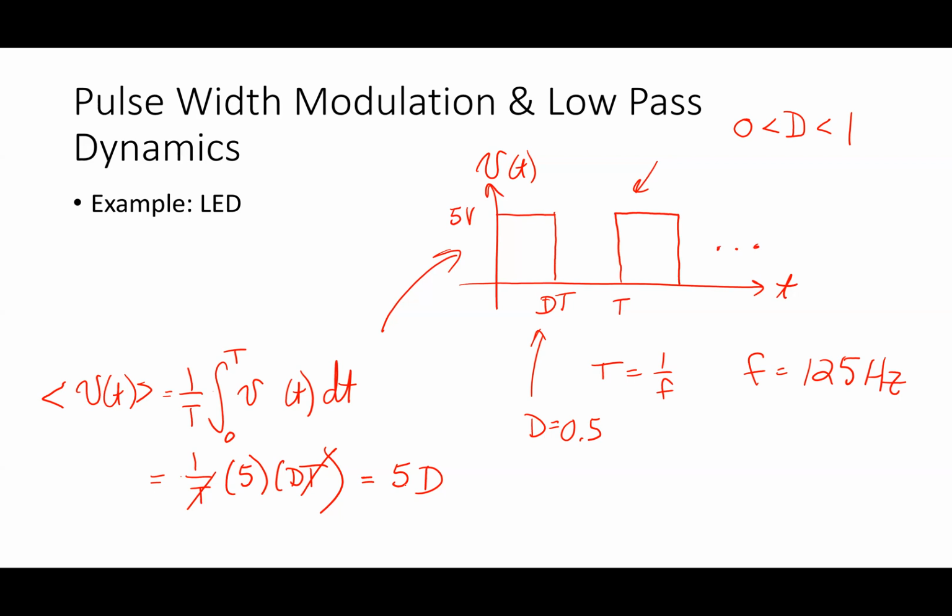So what it has, like most function generators, this guy has a duty ratio command, right? So he's set at 50%. So if I'm going to take it down to as low as I can get it, take this down as low as I can get it. All right, so I'm going to drop the duty ratio down. I think I have to hit enter first. So I'm going to do 20%, and then I do enter, which is there.